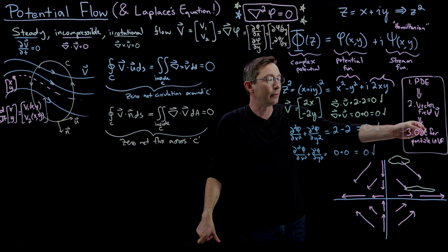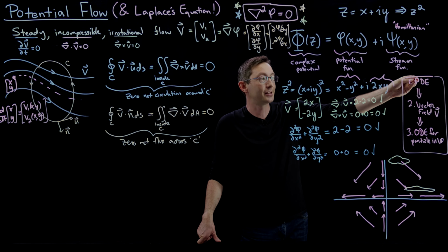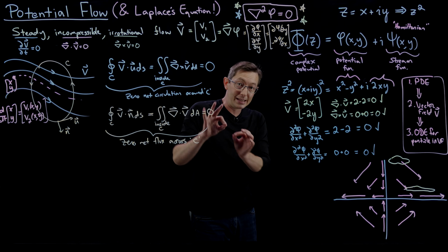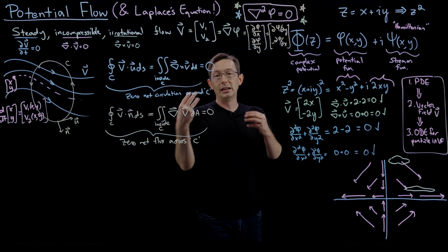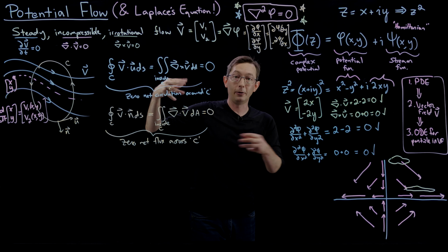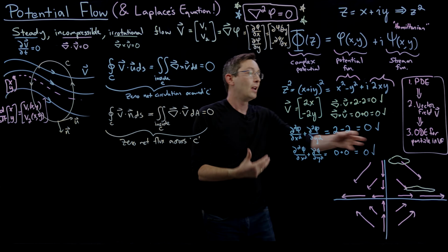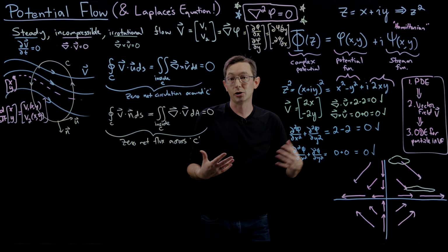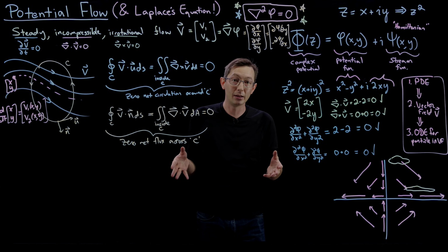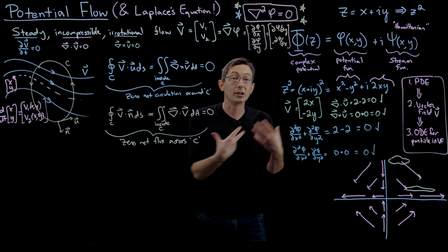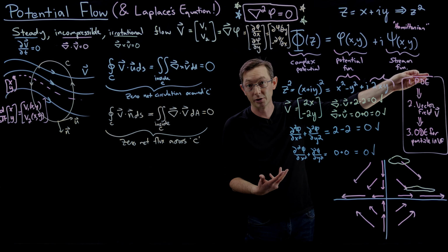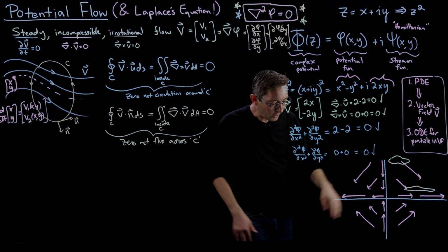And so we're actually going to integrate particles through the Navier-Stokes vector field, which is the solution of the Navier-Stokes equation. That's one of the most useful tools we have for visualizing fluid flows, is integrating particles and seeing where they go. You know, in smoke visualizations, in old wind tunnels, you'd put a cigarette or a piece of incense in the wind tunnel, and you'd see where those particles collect. And that tells you a lot about the structure of that flow, looking at where particles collect. When we unfortunately or accidentally drop pollution in the ocean, we can see where it goes, or we can predict where it goes by integrating those particles through the Navier-Stokes vector field, which is the solution of a partial differential equation. Very useful stuff. And you can picture that here.